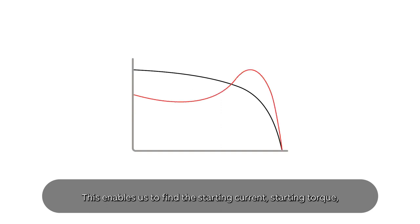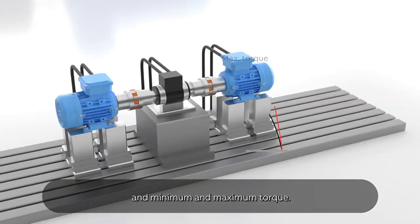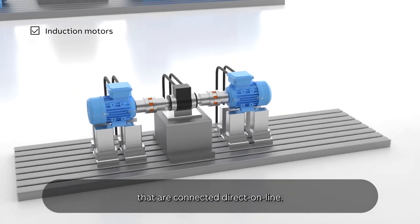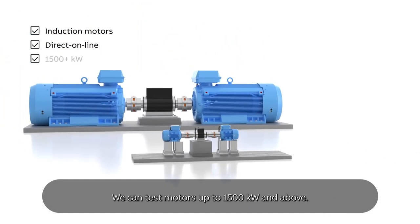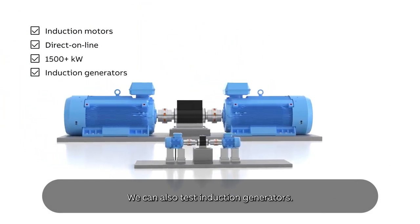At the same time, we plot current and torque against speed. This enables us to find the starting current, starting torque, and minimum and maximum torque. This is the process we use for testing induction motors that are connected direct online. We can test motors up to 1,500 kilowatts and above. We can also test induction generators.